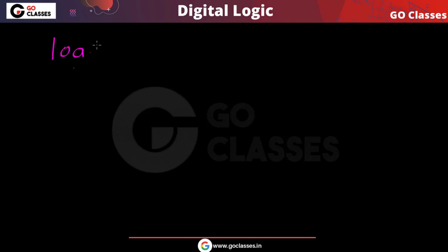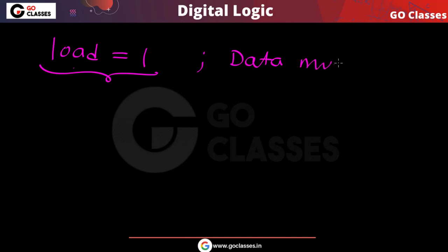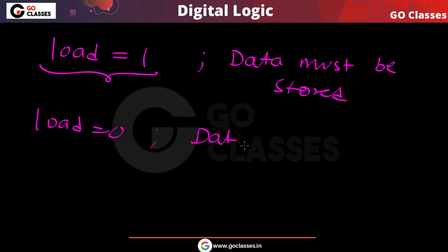When this load is 1, then the data must be stored. So if you want to store the data, you make load equal to 1. And when this load is 0, then the data should be unchanged, or retained. So this is what we want.